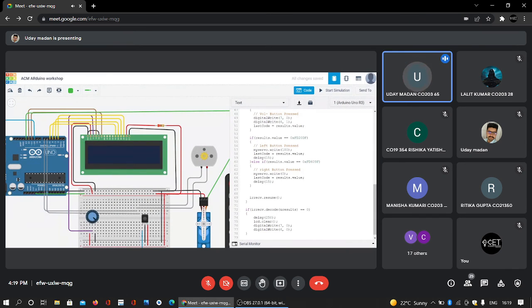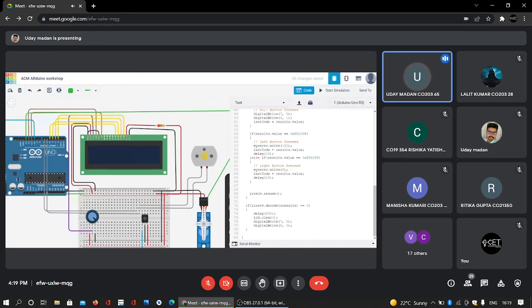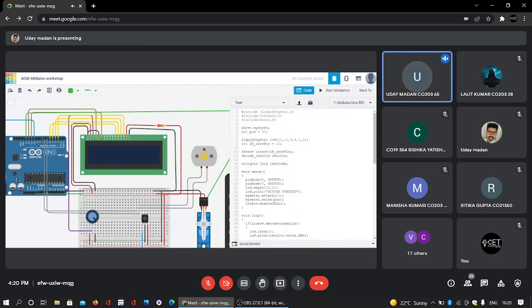And at last we'll set our servo motor, that is the steering motor of our car, back to its initial position, that is 90 degrees. So my car steering wheel will come back to its position when there is no signal. So this is the code for driving the car. We'll test it now, to see if everything is going fine or not.